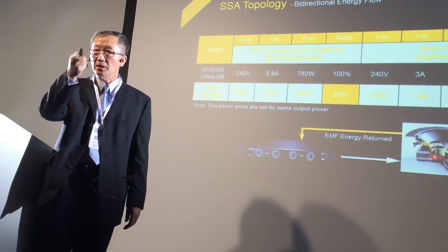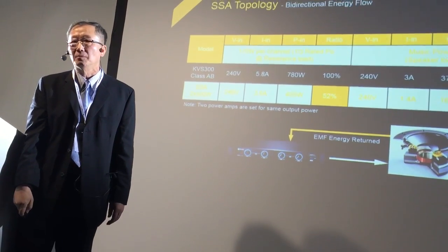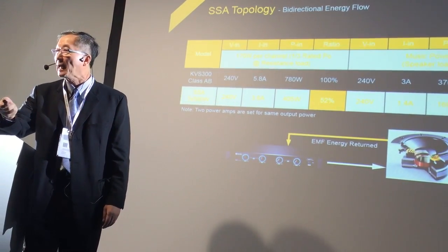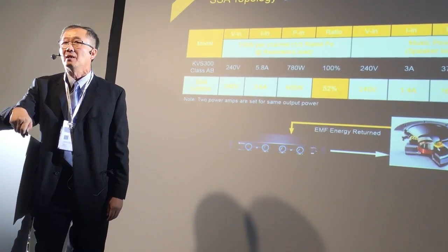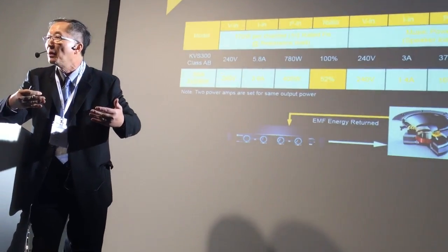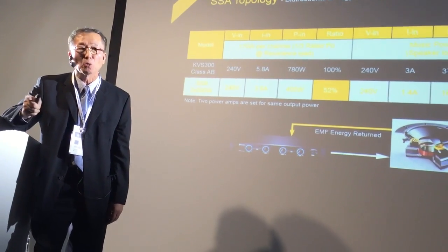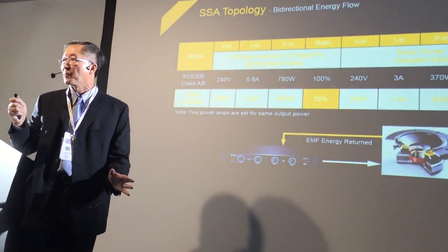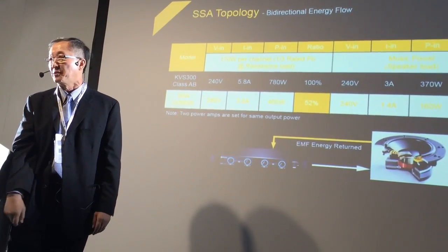However, when the signal goes from whatever level back to zero, the speaker will not stop. The speaker still needs to move because of the leftover energy in the speaker system. Then, in terms of sound quality, you have less control, maybe the bass is not tight. Also, in high power applications, the energy is so large it can destroy the amplifier. At certain frequencies, the energy becomes so large that the amplifier fails. That's one of the reasons.